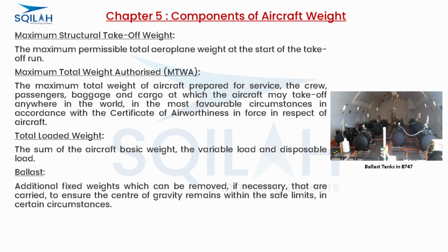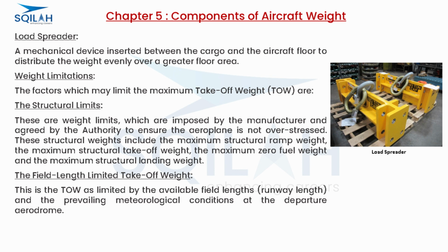Ballast. Additional fixed weights which can be removed, if necessary, that are carried, to ensure the center of gravity remains within the safe limits, in certain circumstances. Load spreader. A mechanical device inserted between the cargo and the aircraft floor to distribute the weight evenly over a greater floor area.